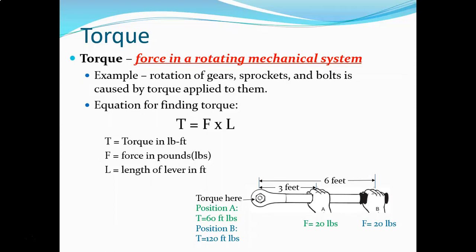That can be translated through calculations into other units, like inch-pounds or Newton meters, but it comes from the distance. You may be using meters or inches. If you're using inches, it would be 36 inch-pounds at that distance, because instead of 3 feet, it would be 36 inches.